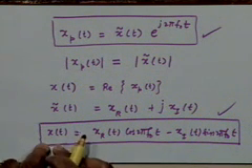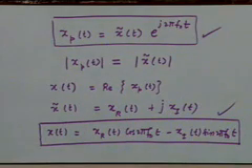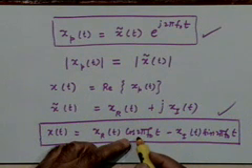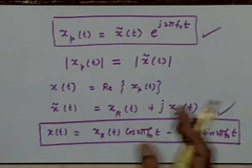So the band pass signal can always be thought of as a product of a suitable low pass signal with a carrier signal. That's what it really boils down to. A very significant result. For every band pass signal there is a corresponding low pass signal, in the sense that from that low pass signal I can generate the required band pass signal by a simple frequency translation operation.